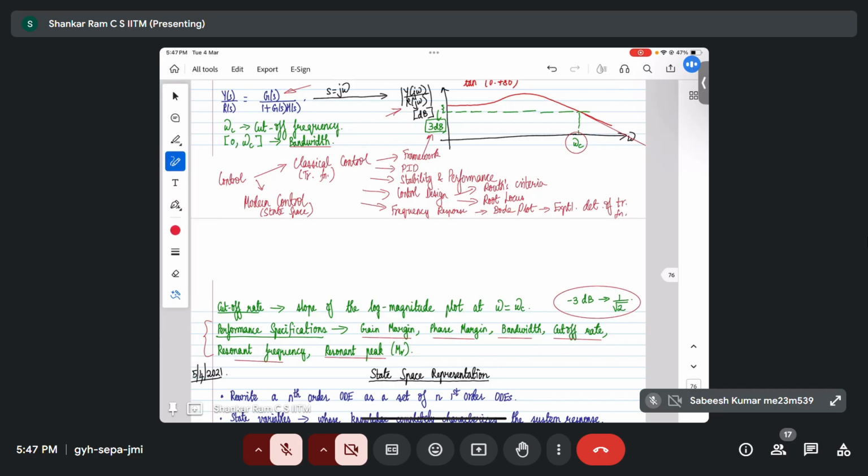That is the definition of frequency response, because when we give an impulse, we call it impulse response, step response also, right? Why, when we give a sinusoidal input, do we not call it a sinusoidal response? So it so turned out that there is a history that we need to respect, Roshan. If we look at it, the sinusoidal input is characterized by frequency: sin omega t and cos omega t. So that is why people call it frequency response.